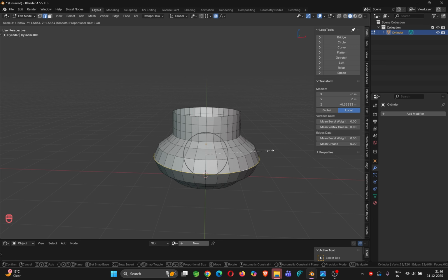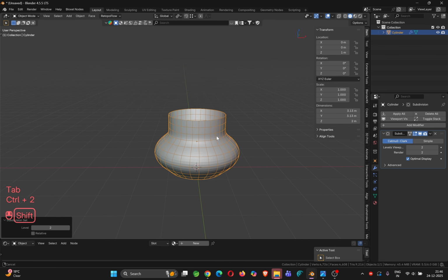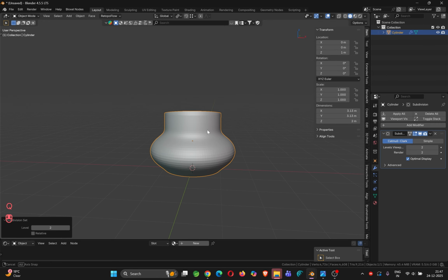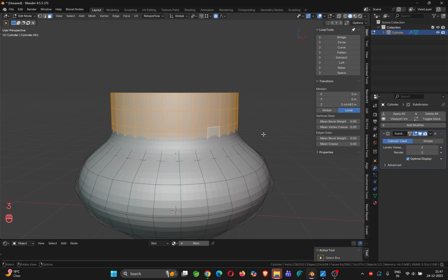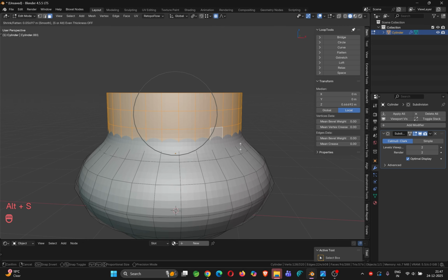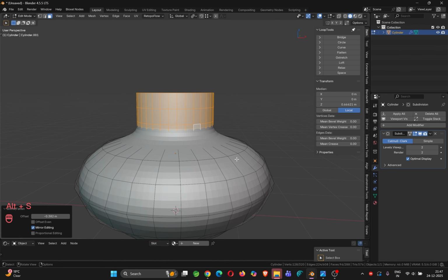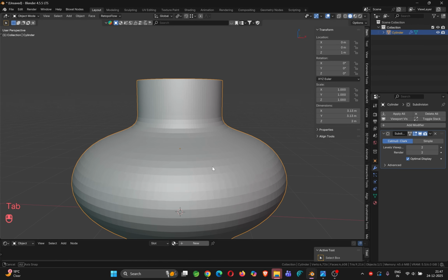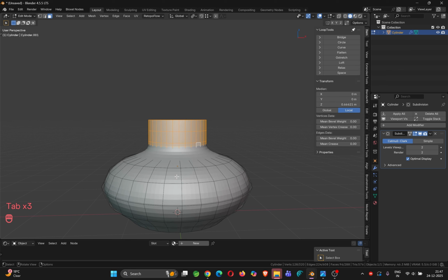So maybe you will apply a shape like this and just apply subdivision later. Let me disable the wireframe for the time being, and maybe you want to scale it along normal like this. Let me disable the proportional edit. But the problem here is that you see this, some faces are smaller, some places are longer, and that creates a lot of problems later in the pipeline.